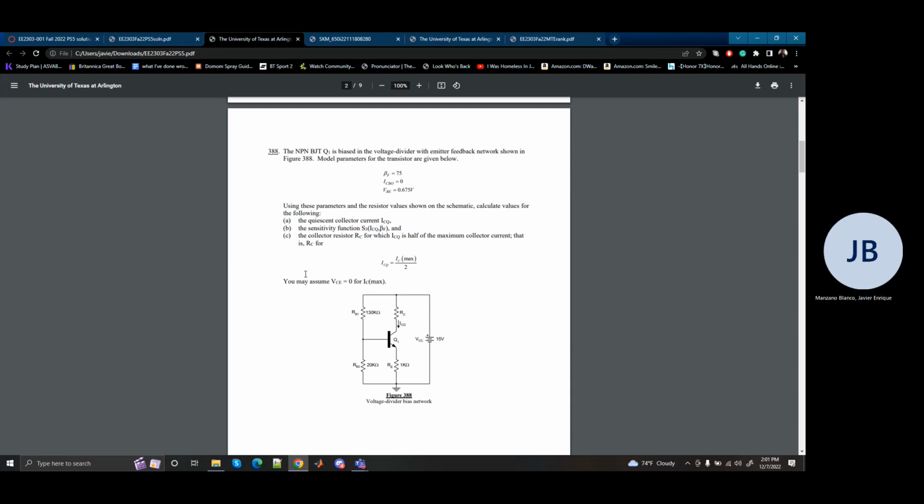Right. So if I'm doing the Thevenin's resistance, I short this out. These two are now in parallel. That's RBB. VBB is just gonna be a voltage divider. Give me that. So now I have this. Now I can find IB.